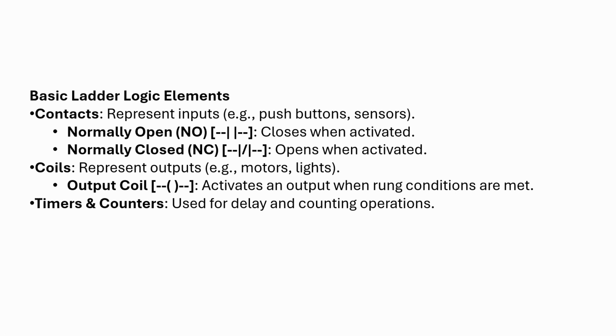Some of the basic ladder logic elements, and we're going to see these more as we get into the software. But contacts, they represent inputs like push buttons or sensors. You have normally open contacts, like what you see here. They close when they're activated, and normally closed contacts, they open when they're activated. And so you can see the little difference in what they look like.